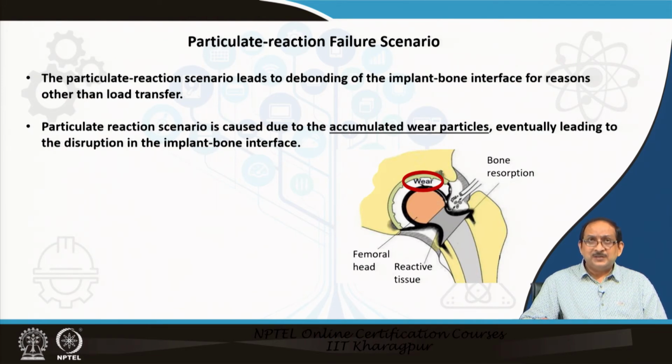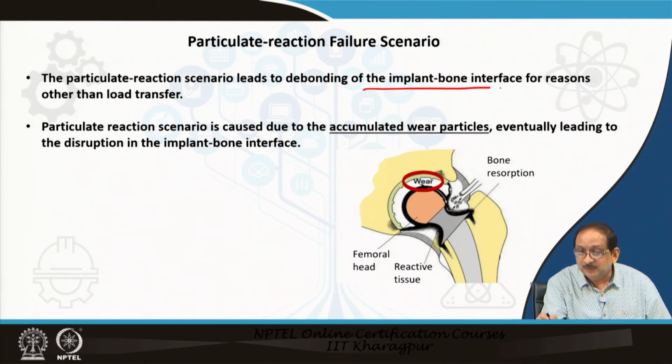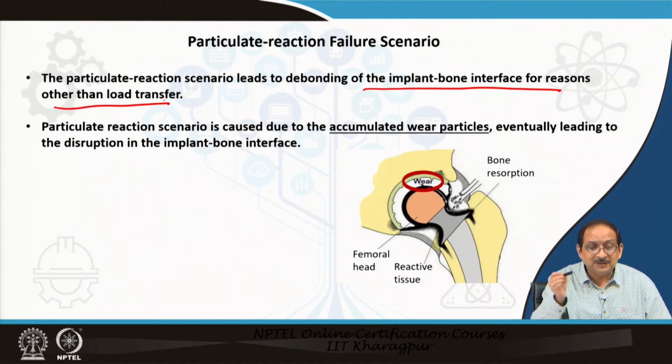Let us now discuss the particulate reaction failure scenarios. The particulate reaction scenarios leads to debonding of the implant bone interface for reasons other than load transfer. The particulate reaction scenarios is caused due to accumulated wear particles, eventually leading to the disruption of the implant bone interface.